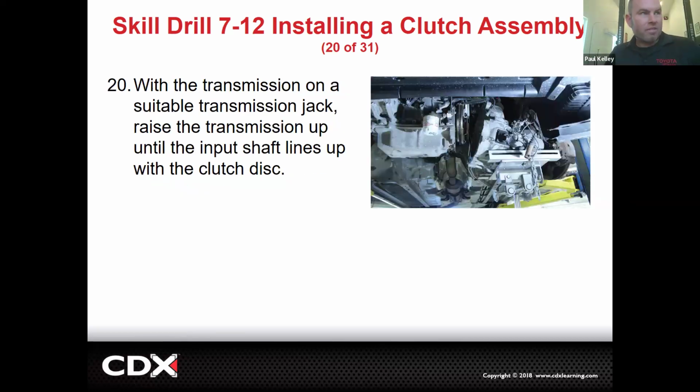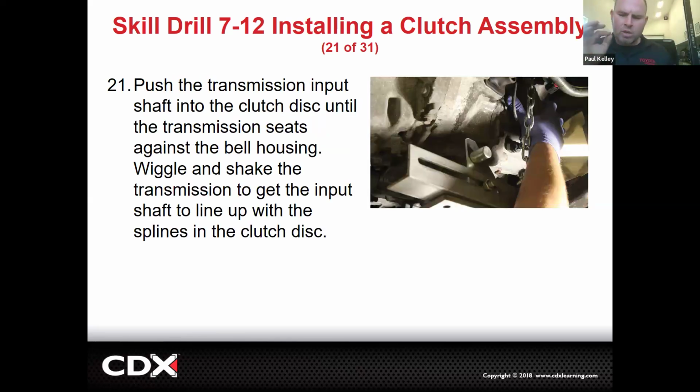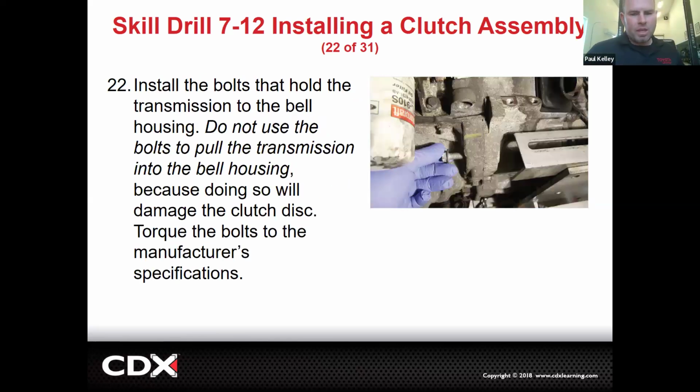And so if it's front wheel drive, you can see this transmission jack can get it up into place, but you notice that transaxle is not centered. That's why you can use these little knobs on the transmission jack, get everything level, maybe roll it this way, roll it this way, level it this way, level it that way. And it should just go. Okay. Very good. Like that.